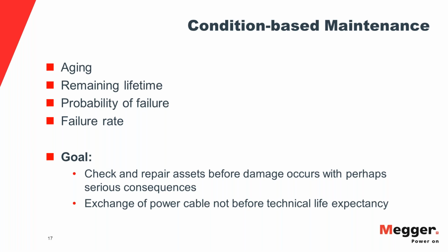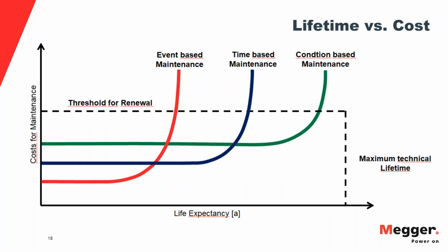years if it's not necessary, because you say, XLPE cables, you should get 40 years out of it. That's typically the nominal life expectancy for design, or maybe even 50 years. But it's expected that you're probably not getting the same life out of the extruded cables like we did out of the PILC cables. And then this is pretty much the investment side of it.